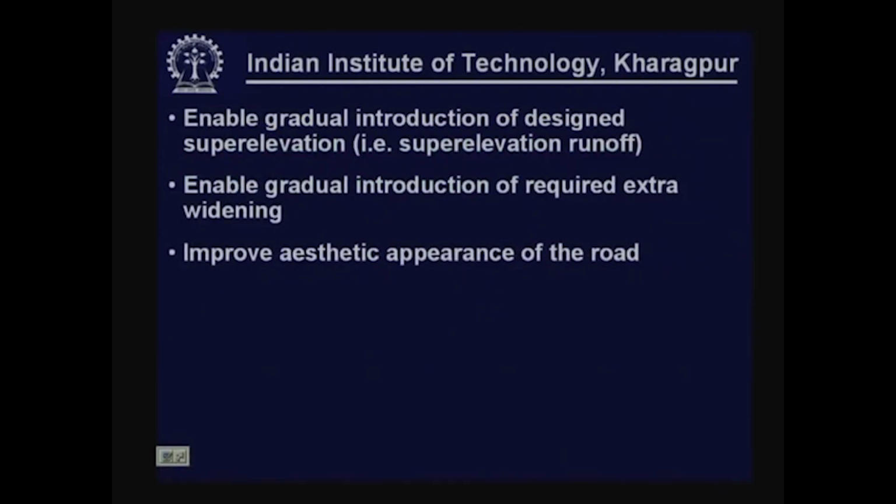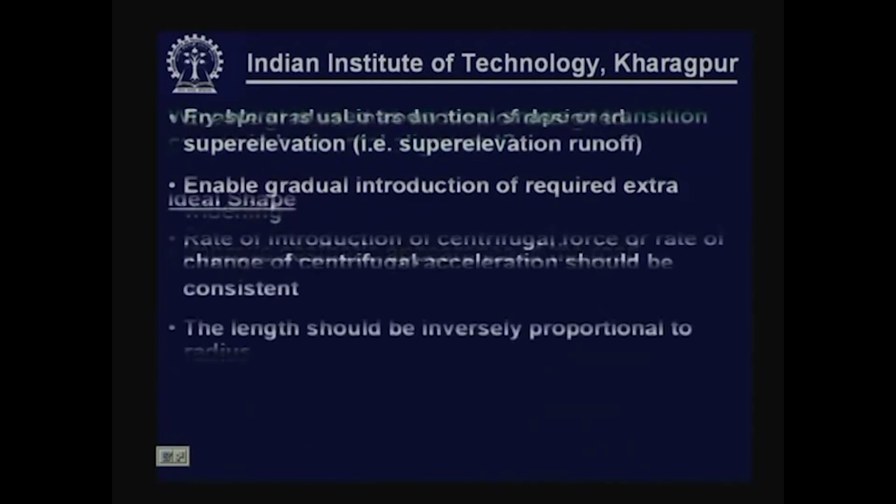4, enabling gradual introduction of design superelevation, that is superelevation runoff, particularly this length, and also enable gradual introduction of required extra widening. Finally, it improves the aesthetic appearance of the roads. So, those are all the advantages of using transition curve.